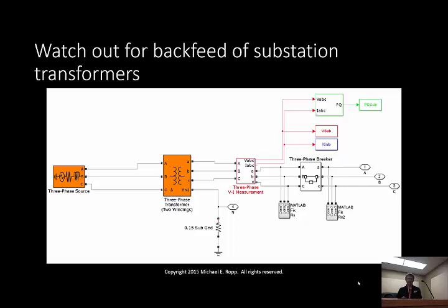The main mitigation strategy for this right now is 3V0 relaying. You usually don't apply a grounding transformer here, and I'll show you the reason why. It has to do with the overcurrent protection of the grounding transformer. What we would like to be able to do for the future is we think there are some ways to deal with this at the DG site using symmetrical components. Negative sequence relaying is what we're going to be looking at. So that's where this is headed, we think.